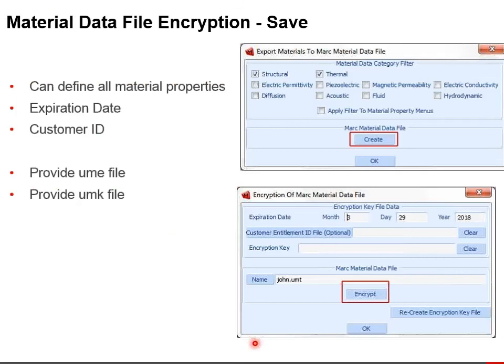Next thing we did having to do with materials is a continuation, also something that we introduced lately. We introduced that you can have your material data in an ASCII file. That was called the UMT file. We've extended that, so you can build up material models in Mentat, and then write out an ASCII file.